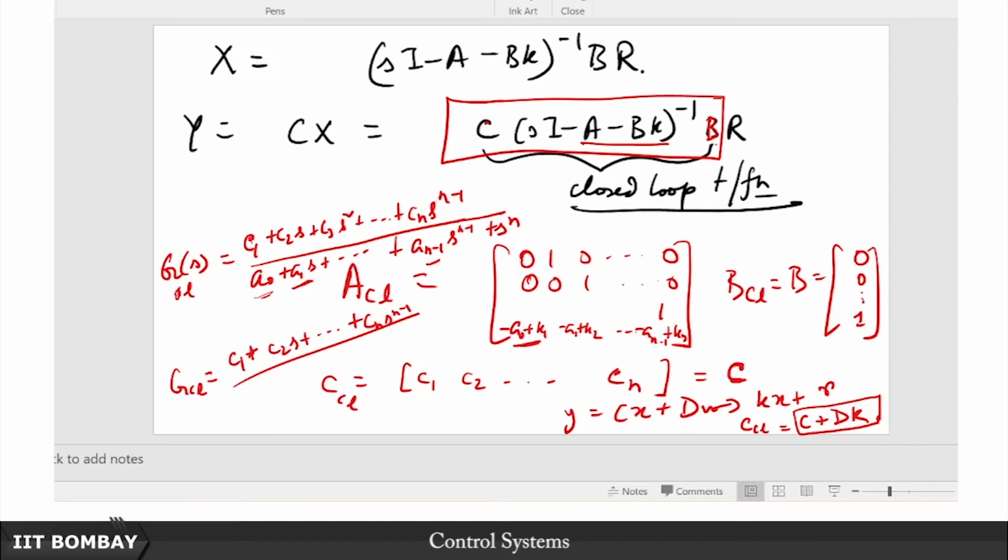They talk about discretizing this system into a discrete time system, and then in the discrete time domain, using different rates of sampling, you can trick the system into thinking that, although the continuous time system's zeros are in the right half plane, the corresponding discrete time system's zeros are, yeah, the continuous time right half plane matches with the outside of the unit circle in the discrete time domain.